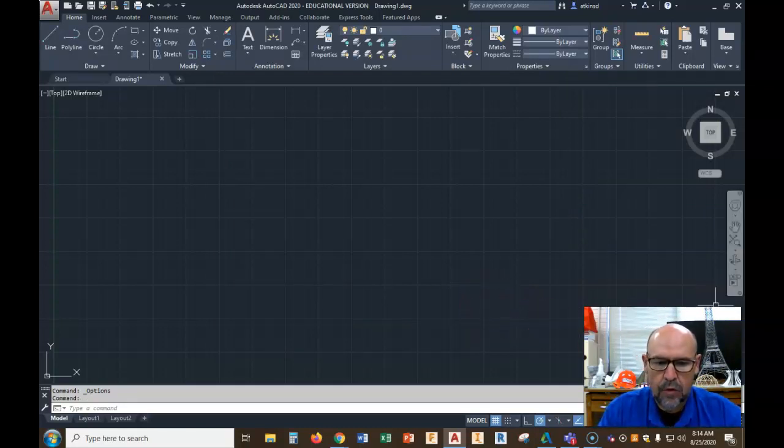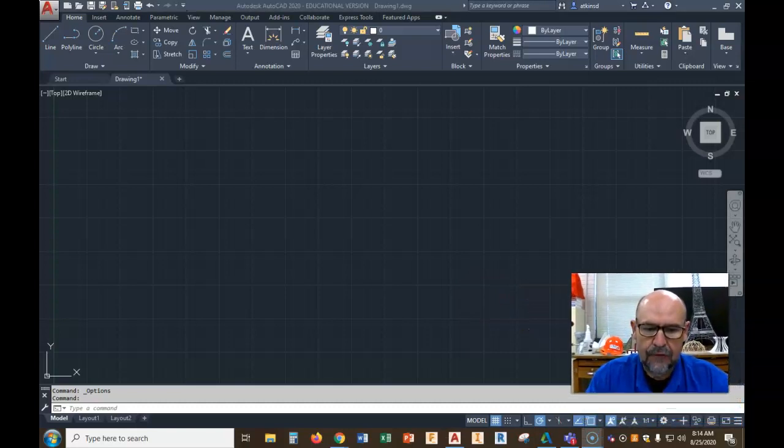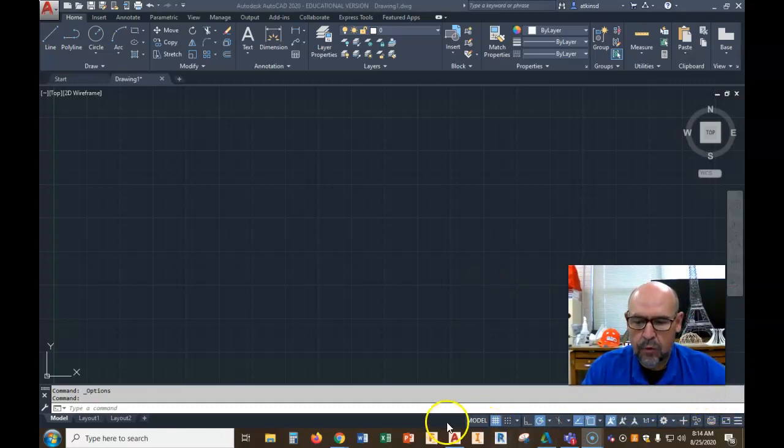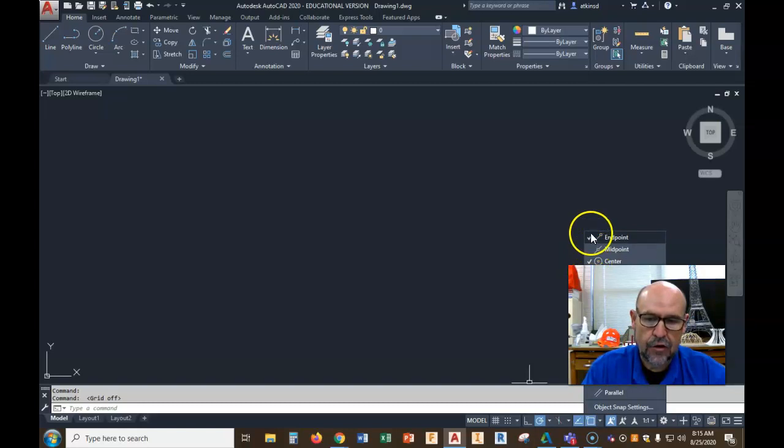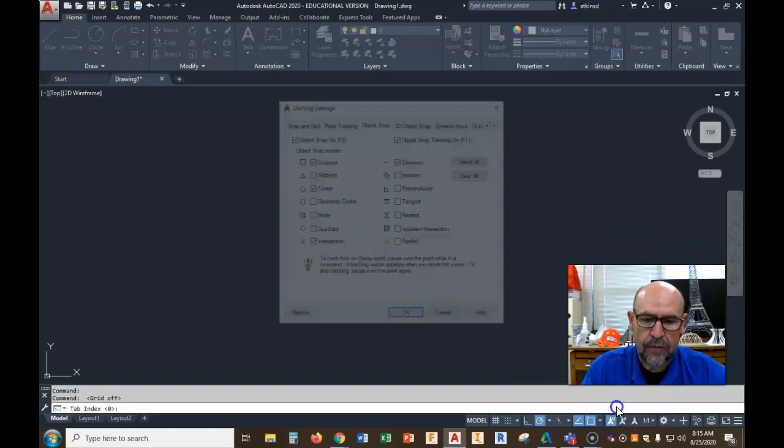The next thing that we're going to want to do, and I'm going to slide my view screen up just a little bit, is look down here at the bottom. We talked about the grid mode. I typically do not work with the grid mode on, so I'm going to cut it off. You can cut it back on if you want to. The other thing we're going to do, we're going to leave it in orthographic. We're going to come over here and hit this drop down. What we're going to do is cut our object snap on. Now, we could cut them on from here. I could click the ones that I want going down through here. And by the way, you want all of these down to where it says intersection and extension. So from endpoint to extension, I usually cut on. But I will do that from this setting box.